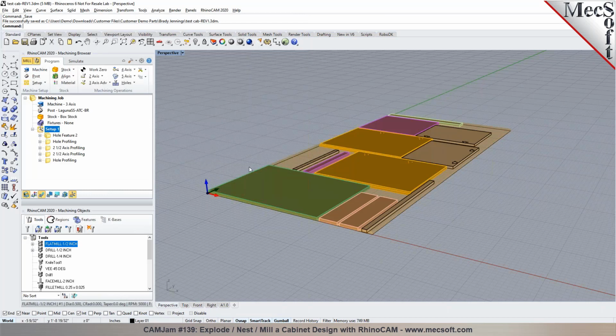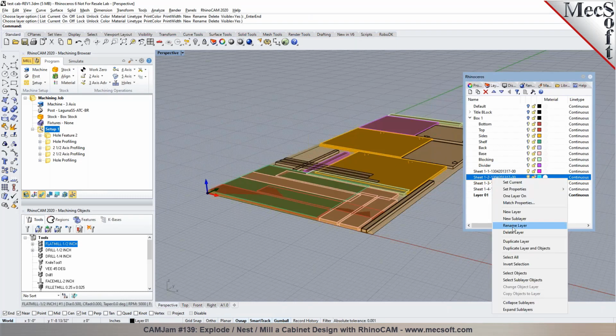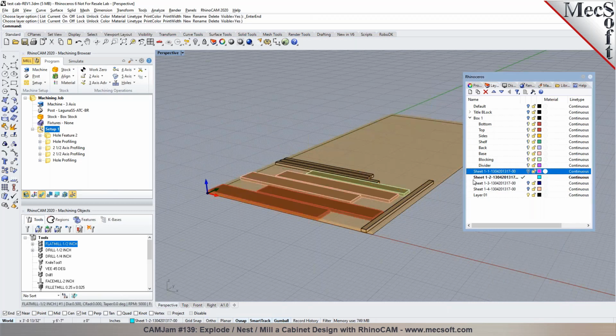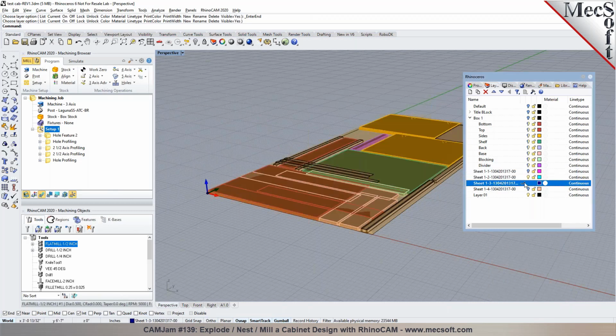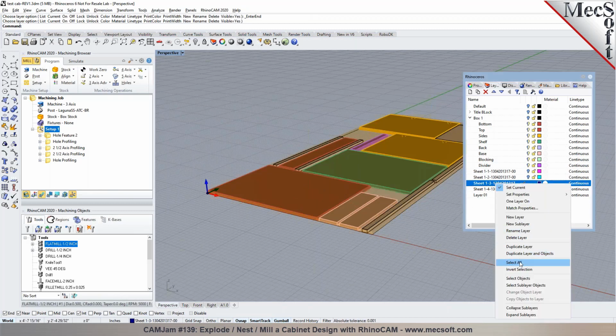Now, when I want to program, let's say, another part, in this case, I'm going to take the sheet number 2 that we have in here, right? I'll right-click and say export. I'll say select objects, select all on the sheet. I'll hide this sheet right in here. Or let's pick a different one. Okay, this sheet has more objects in here. So right-click, select objects or select all.